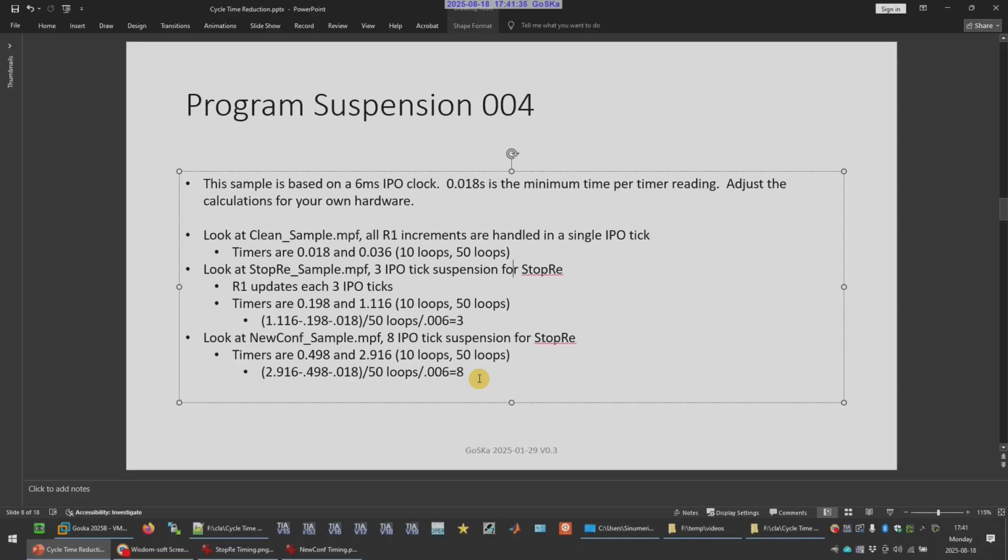So these things can be super useful, but they need to be used very sparingly. Otherwise, you just start building in delays. There are some systems out there that have a very heavy prog event file that does some hefty kinematic work, shuffling around kinematic data, that have a pile of NewComps to the point where when you hit cycle start or reset, you as the operator will notice a delay. So you have to be careful with these. Use them sparingly, but if you need them, they're perfect.